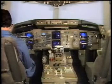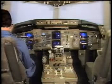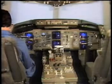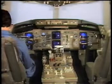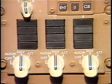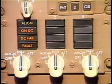The following sequence of indications appear on the IRMP and the Captain's Electronic Attitude Director Indicator, or EADI, Electronic Horizontal Situation Indicator, or EHSI, Vertical Speed Indicator, or VSI, and on the First Officer's Radio Distance Magnetic Indicator, or RDMI. On the IRMP, these left IRU annunciators come on for approximately 2 seconds: align, on DC, DC fail, and fault.